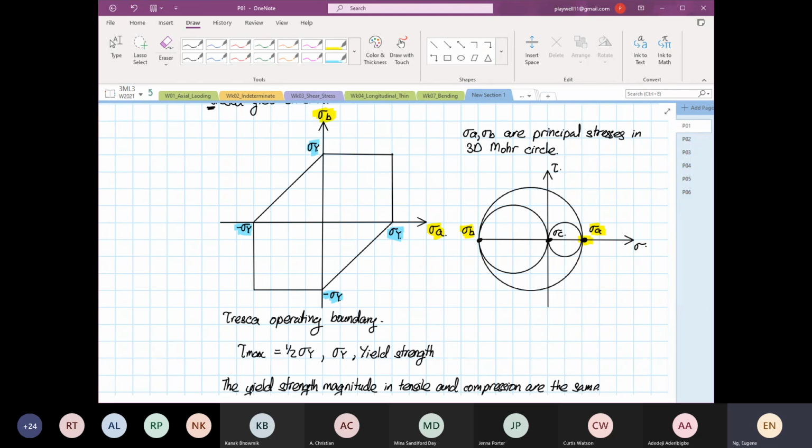Their operating boundaries are about the same. The only thing that is different is in Mohr's criteria, which is based on ceramic or brittle material, where the compression is bigger compared to tensile. Now what does this graph, like stress A and stress B, mean? Your stress state must be inside this diagram or boundary. So your principal stresses have to be inside that box.